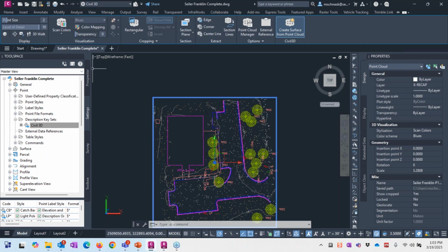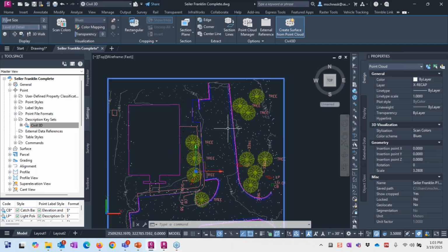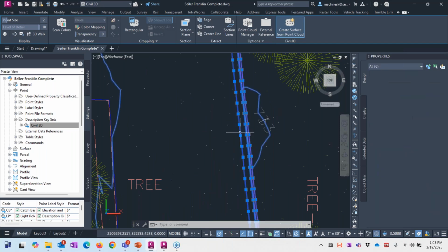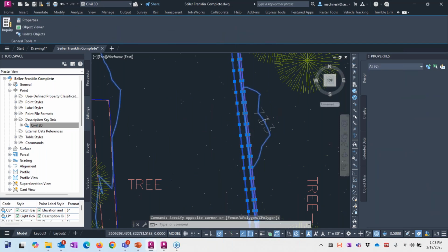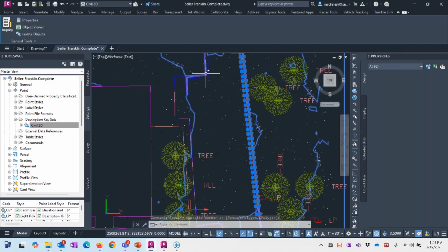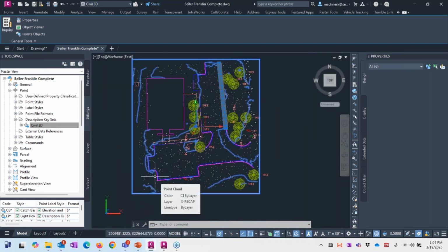I forgot to tell you, there is a caveat with bringing Land XML. These came in as international feet, and I had to take all my stuff and scale it up by a factor of 1.000002. So I converted them to US survey feet. If I brought them in as a DXF, they come right in the spot. I got a case with Autodesk to get that fixed.